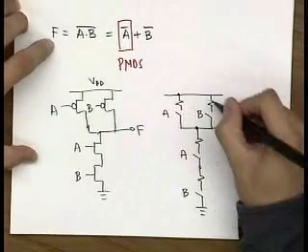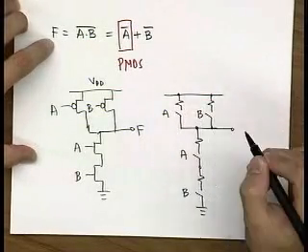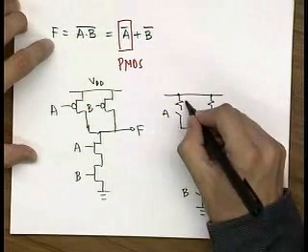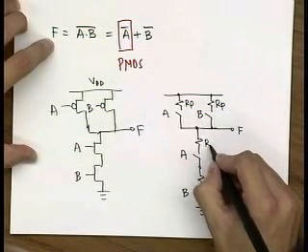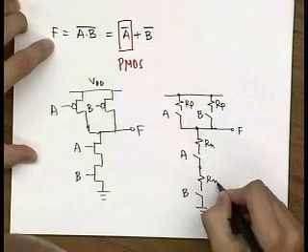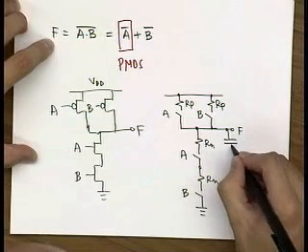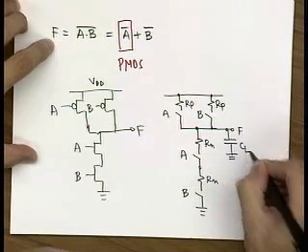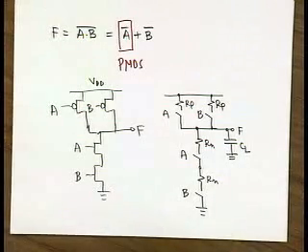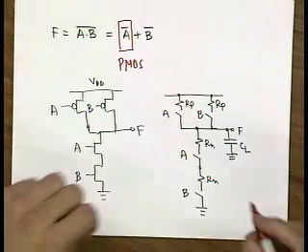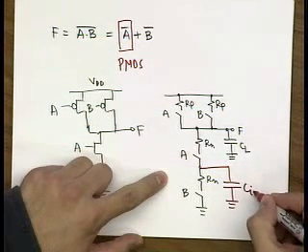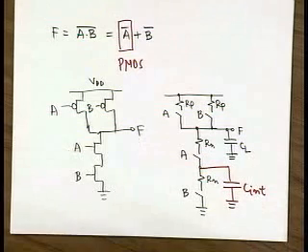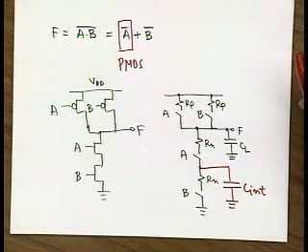Let's assume for a moment that all transistors are the same. So we have Rp for the PMOS, and the NMOS transistors are the same, Rn and Rn. And we have some load at the output. In addition to that, we also have this intrinsic capacitance. So now this is getting a little bit complicated for delay analysis purposes.